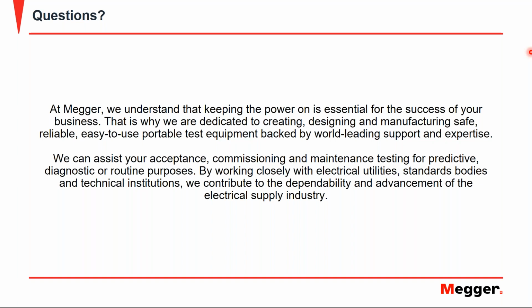Is tan delta test as applicable to high voltage cables as it is to medium voltage cables? If we look to the IEEE 400.2, over there are tables for Tangens delta in it, and they are mainly only focused on experiences gathered with 15 kV and 25 kV rated cables. A 35 kV class can be used for those tables as well, but if you go higher in voltages, those tables have almost no meaning anymore.